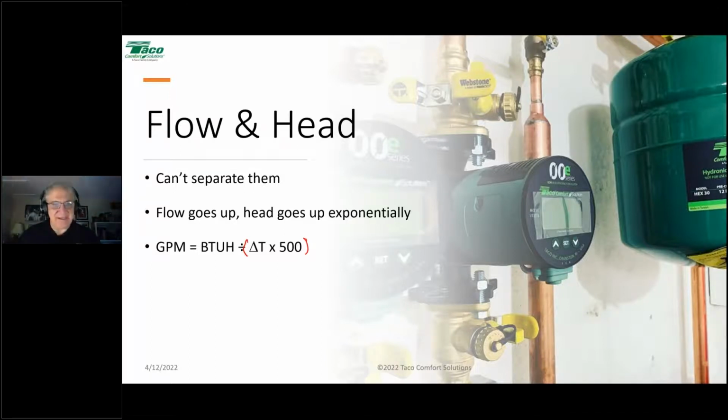Glycol weighs different, it has a different specific gravity, and it has a different specific heat. The only thing that stays constant is the 60. The thing about glycol is every manufacturer is a little different. They've got their own formulas and their own mixtures. So the number we know is going to go down, but by how much is going to depend upon what you use. A good general, get-you-in-the-ballpark number, and I'm not a fan of those, but this will help you understand the impact.